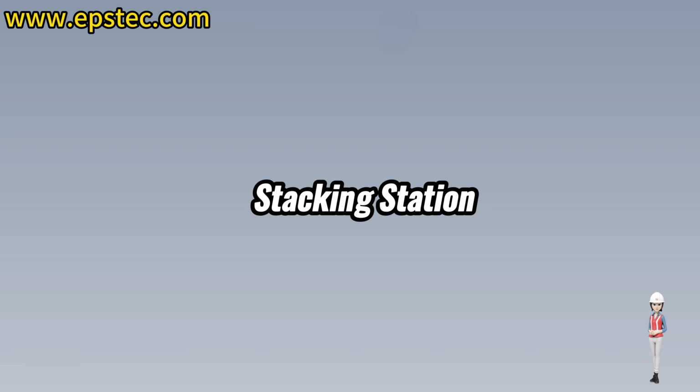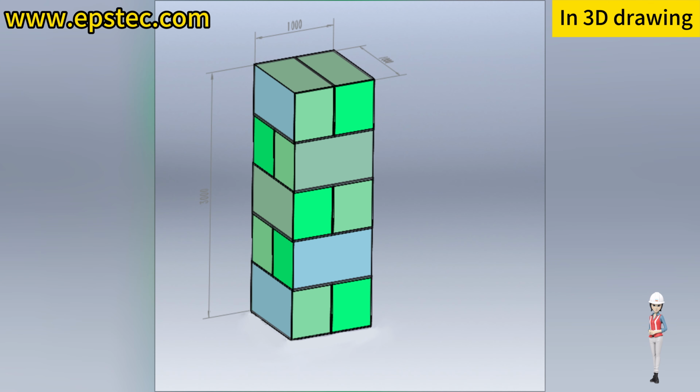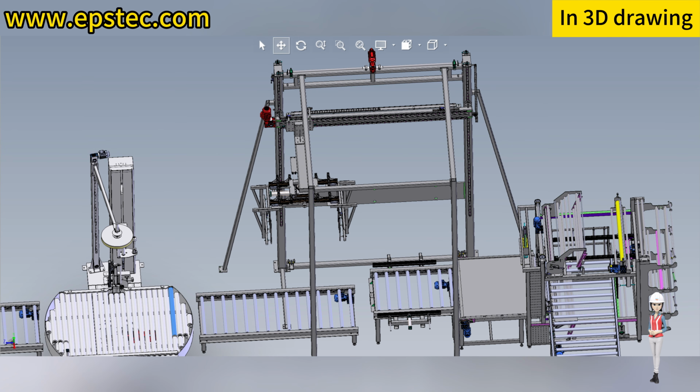Stacking station. The stacking robot arm can rotate 19 degrees. The first layer does not rotate. The second layer rotates 19 degrees, and so on, to achieve cross-stacking. When the number of stacking layers reaches the set number, the whole stacked EPS packages are sent to the PE film wrapping machine for packaging after the conveyor is started.